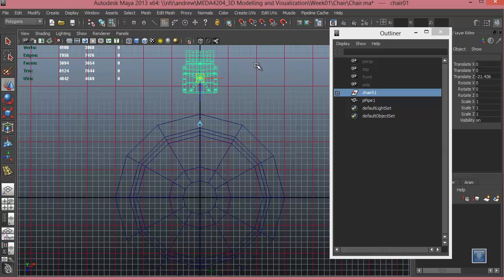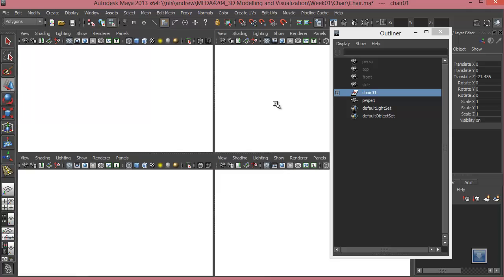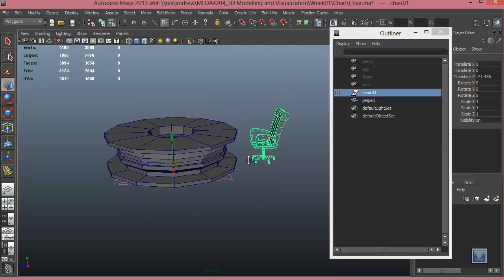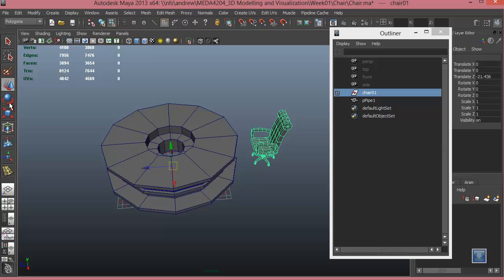Okay, insert key is usually placed above the delete key, and when I press the insert key, it gives me this option to move the pivot point, and I can press the grid snap so that I can snap it to the center. I'll turn it off, press insert once again to come back to move tool. Okay, now if I rotate, I can take the rotation tool, and if I rotate, I can see that it is going perfectly around the table.